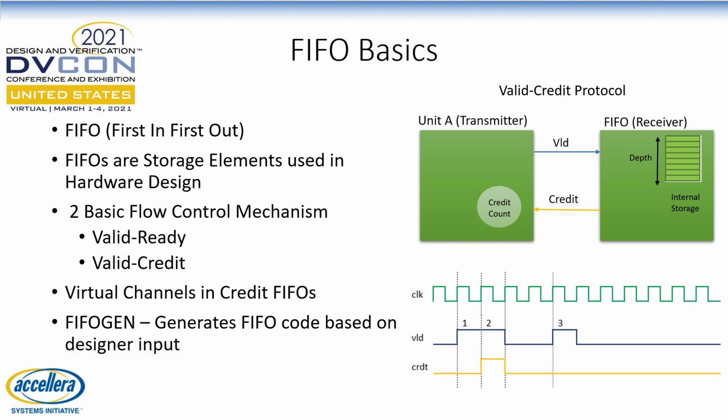To complicate things further, sometimes we have virtual channels, in which multiple packets of different types, or packets belonging to different credit classes, are transmitted over the same physical interface, but we want to maintain independent flow control. In this case, if there are n credit classes, we partition the depth into n regions, and the sizes of these n regions are stored in n credit counters in the source.